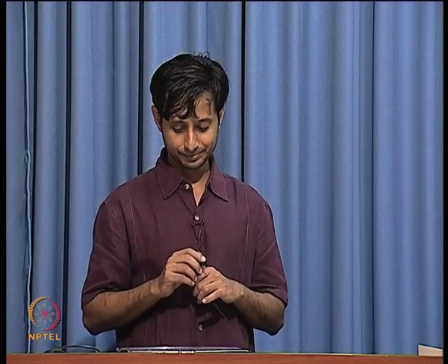So, as far as our low noise amplifier is concerned, we want to make sure that the characteristic impedance of the antenna is equal to the input impedance of the low noise amplifier. I said the characteristic impedance of the antenna is chosen to be 50 ohms. You design the antenna so that its characteristic impedance is 50 ohms. That means that you would want your low noise amplifier to have an input impedance of 50 ohms. All right.